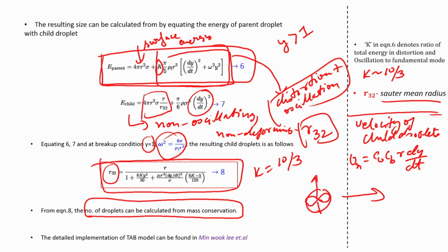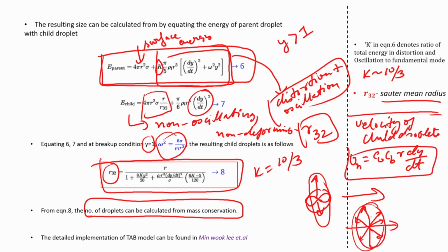As the droplet spits out, it spits out in those perpendicular directions. Now, it can happen in a plane anywhere around that perpendicular plane. So, if it is going like this, the daughter droplet can come anywhere in this plane, all of these are perpendicular. Velocity magnitude is given, the plane is given, but the exact direction is completely arbitrary. There is a certain randomness, because you can never predict exactly how it is happening. So, this gives you the velocity of the daughter droplet. Once again, this Cv is of the order 1.